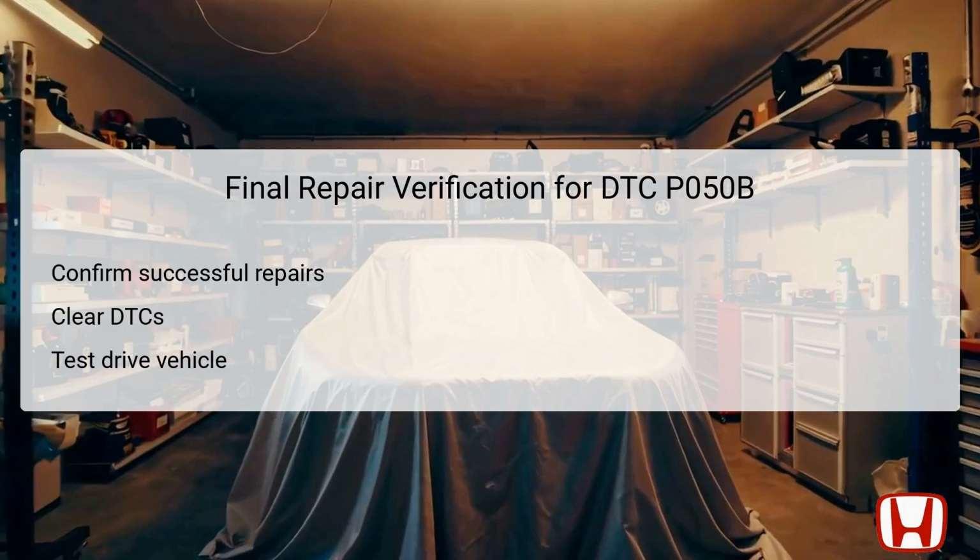Following this, it's essential to take the vehicle for a test drive to monitor and ensure that the cold start performance is restored to optimal conditions. Pay close attention to the engine operation during cold starts, as well as monitoring the HDS for any reoccurring DTCs. Successful diagnostics should lead to no reappearance of P050B, indicating that the issue has been resolved satisfactorily.